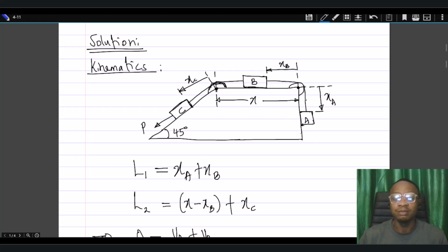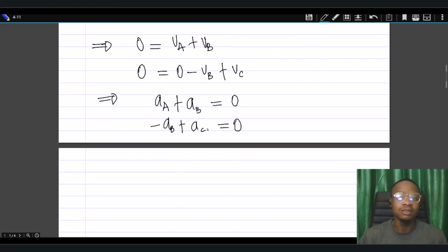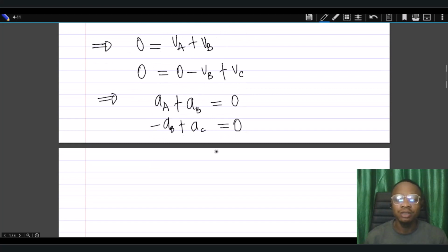So that tells us that when this moves down, AA will be negative, which means AB will be negative, which means B will be going in its own negative direction, and its own negative direction is where XB is decreasing. So it captures the vector relations, so to speak, for the accelerations in this system. So it is better to just stick with it and work with it all through. Okay, so we have these relations. We're going to keep them for now and say this is equation Roman figure 1. This is another equation, say Roman figure 2.